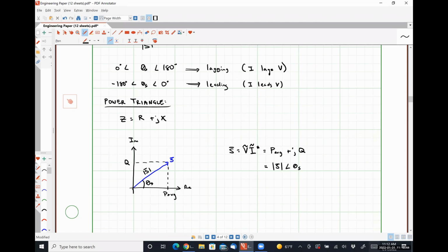You could also, this would be a more complicated technique, use a couple of watt meters and all that kind of stuff to figure out what portion of the real power is actually being absorbed. And then you can get your ratio there. But it's hard to tell what's leading or lagging from that.